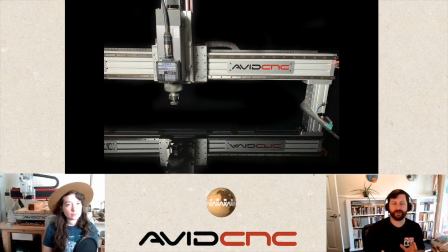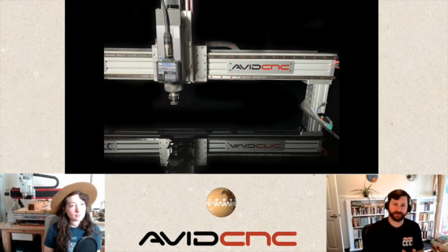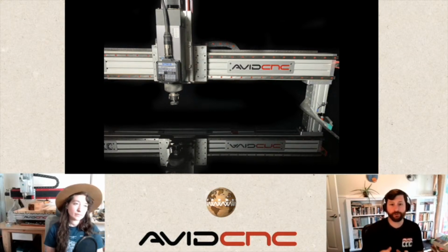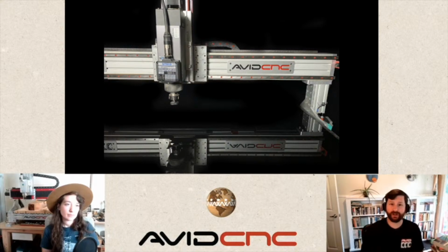So let's talk a little bit about the difference between a router and a spindle. And really the big difference is how the power is being delivered to the motor. With a router, we are essentially reducing the current as we slow the RPM. And so that means if you're using a router, the slower your tool RPM, the less power it has. And so when we talk about chip load for aluminum and brass, typically we're going to be in the lower range of our RPM for our cutting tools.